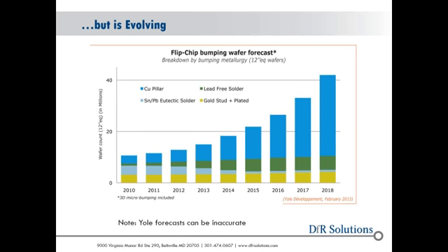And we're going to explain and understand why that is the case. Flip chip has its role in terms of certain designs and certain devices, but wire bond will pretty much dominate for a long time to come. But within that limited flip chip world, the interconnection is going to be increasingly copper pillar.